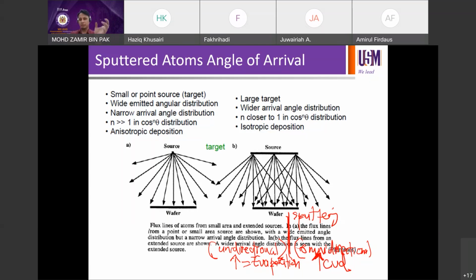But if you talk about uniformity of deposition, the most uniform is CVD, second is sputtering, and the hardest to get uniformity is evaporation, right? It depends on sample condition too. That's just a general process capability. But if you have a sample with the right geometry, the right feature, rotation and so on, you can also ensure good uniformity by the evaporation process.